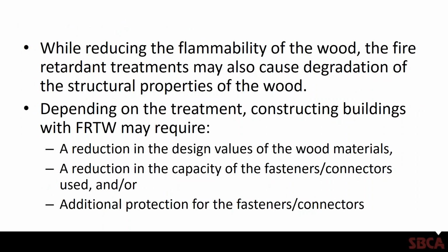So while reducing the flammability of the wood, the fire retardant treatments may also cause degradation of the structural properties of the wood, which needs to be considered in the design. Depending upon the type of treatment that's used, FRTs may require a reduction in the design values of the wood materials, and a reduction of the capacity of the fasteners and connectors that are used to attach the wood materials.